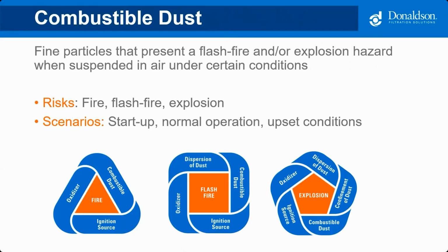An ignition source in pharmaceutical manufacturing is typically going to be a spark created from some machine malfunction that works its way through the ductwork into the dust collector. And so if a fine particle is combustible and then it mixes with air, like the airflow coming into a dust collector, which is usually oxygen, and then it meets the ignition source, it can result in a fire.